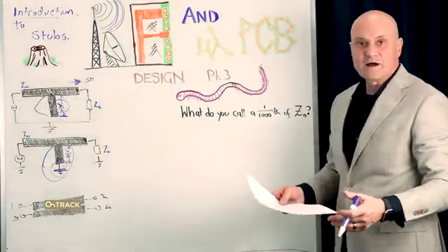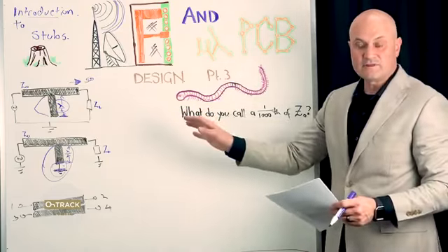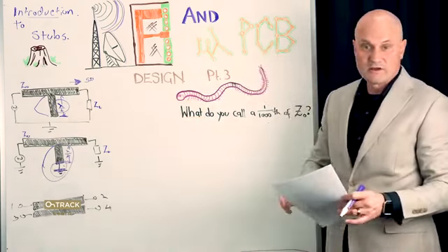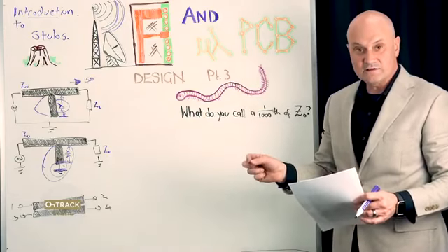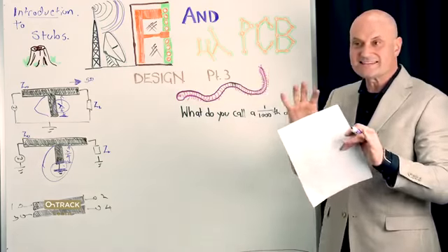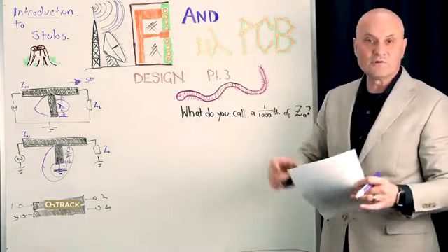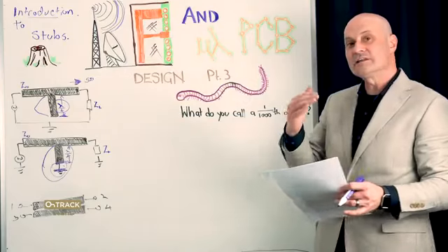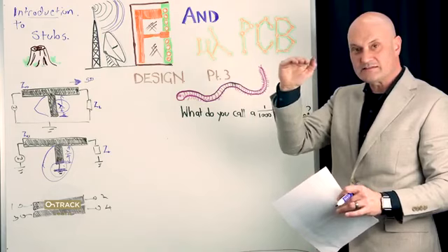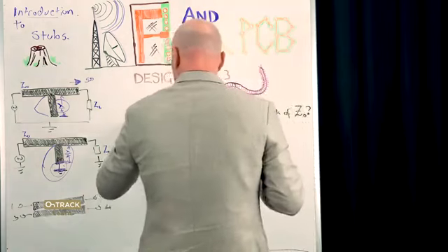So let's say I'm using Osh Park and I'm doing a 4-layer design, and you really want to do a 4-layer design with RF and microwave, because otherwise your feature sizes get much too big and your losses go through the roof from your dielectric losses, because on a 2-layer board you have a much thicker dielectric. So to get the same impedance you need much larger geometries, you need more area, but you're going to get more dielectric loss. So go at least for a 4-layer board where you have a very thin dielectric between the top layer and the next layer down for your ground plane. Okay, so that's what I'm doing, and I'm going to use their 4-layer process.